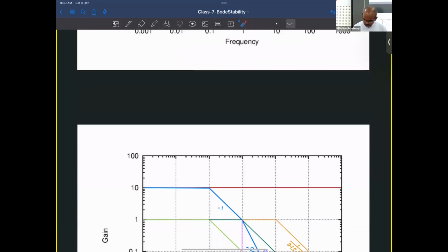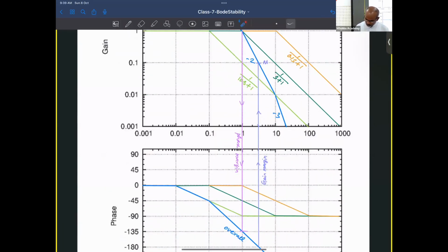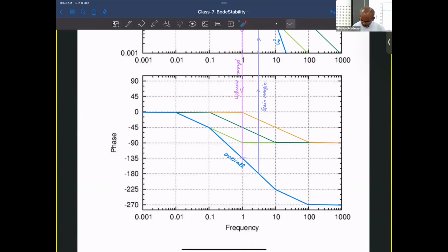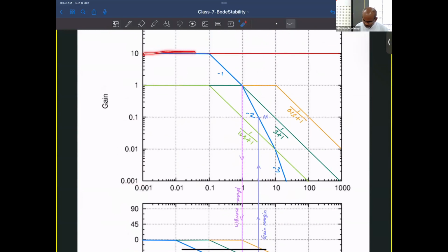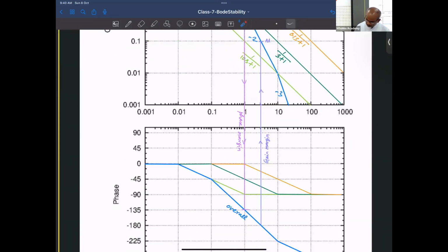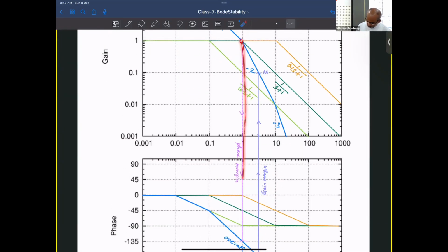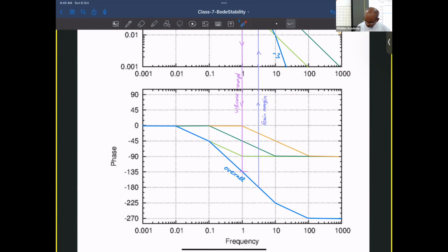Now, getting the phase margin. To get the phase margin, what is needed is, starting from the gain plot at a value of AR equal to 1, nicely draw a vertical line so as to meet the overall phase plot. So what is the value of this phase angle?